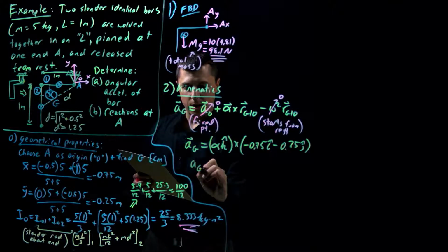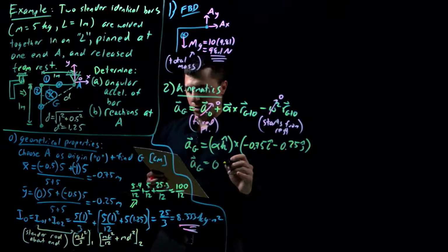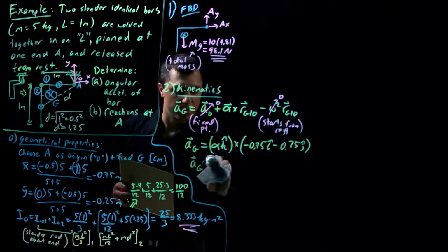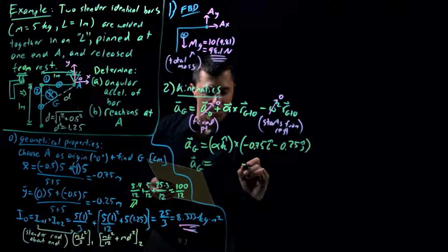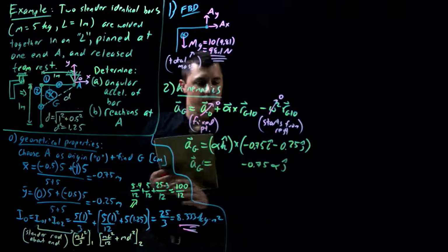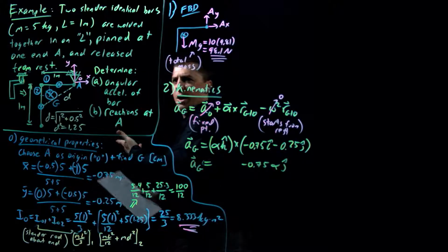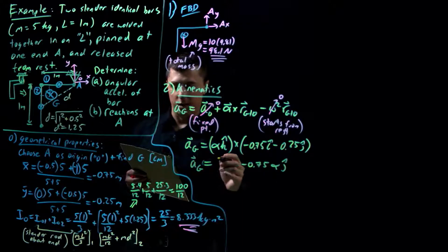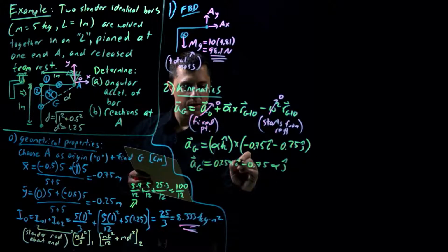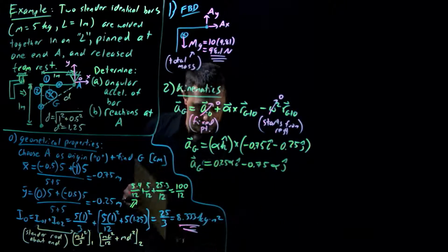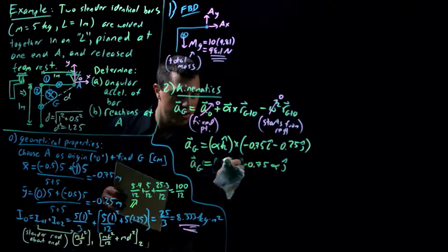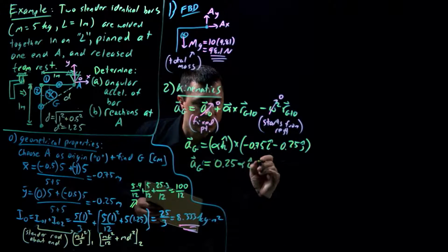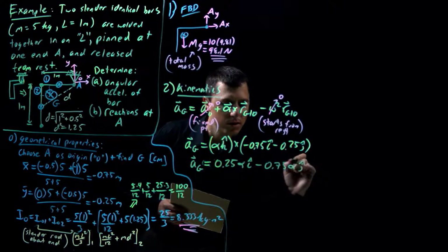So we've got a_G now. Actually, let's put them in order, so we'll put the i hat component first, and the j hat component will go over here. So it'll be minus 0.75 alpha j hat. What's that other term? K hat crossed into j hat. Point to yourself, k hat, j hat is upward, and our thumb points in the negative i hat direction. But this is negative, so that's going to turn that positive: positive 0.25 alpha i hat. Let's write this out: 0.25 alpha i hat minus 0.75 alpha j hat.